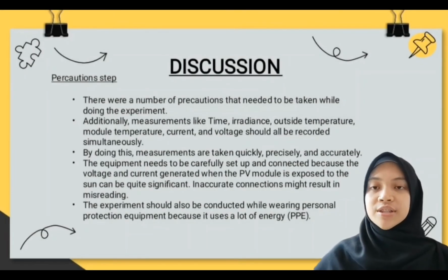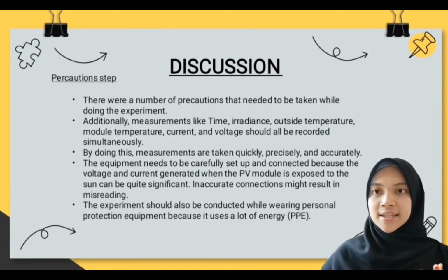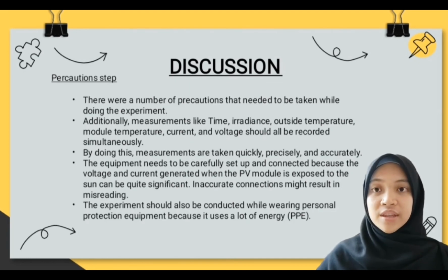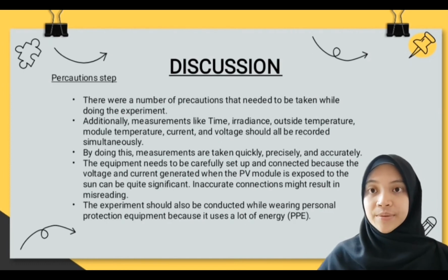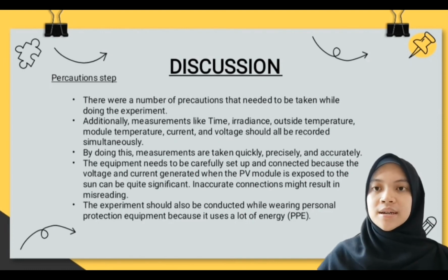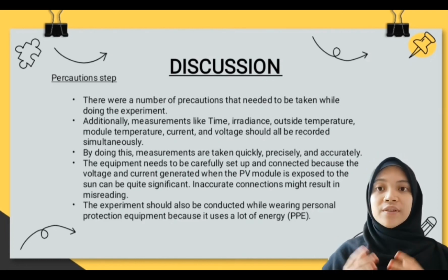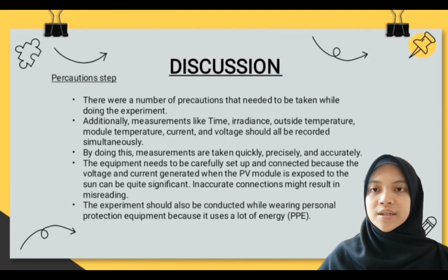Okay, while carrying out this experiment, there are many preparation steps that need to be considered, such as when taking the measurement of time, irradiance, voltage, current, and also module temperature. All of these need to be measured at the same time. Other than that, all the equipment needs to be properly set up and connected, because incorrect connection can lead to inaccurate readings. Finally, this experiment involves a large amount of energy, so we should wear personal protective equipment.